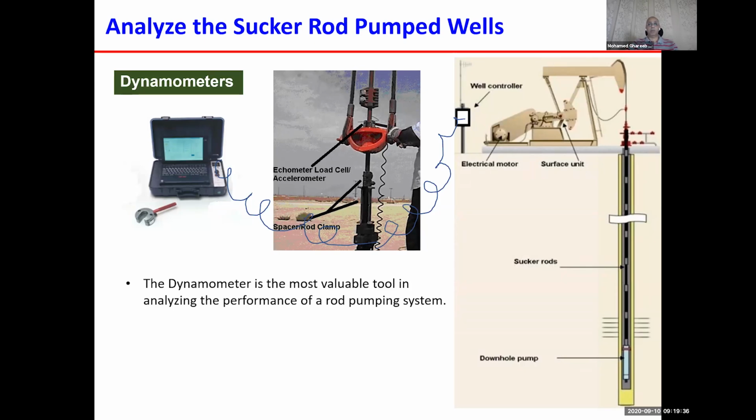What is a dynamometer and what does it look like? Do we have one type of dynamometer or different types? How can the dynamometer inform me about a problem? For example, if I have a downhole pump and one of the valves has a problem, leaking. Is a dynamometer capable of telling me, yes, your traveling valve has a problem? Yes, your standing valve has a problem. No, the problem came from your pump barrel. No, this problem is not from the pump, you have a problem with the tubing. No, all your problem came from the pumping unit, and so on.